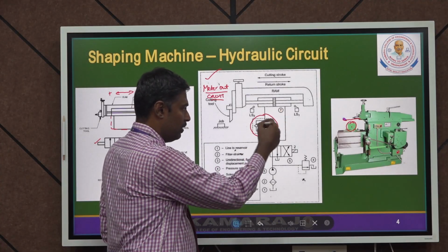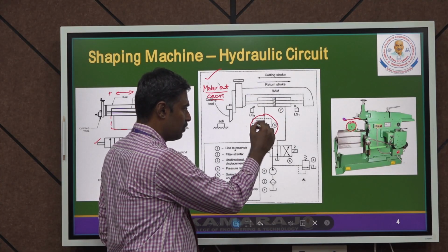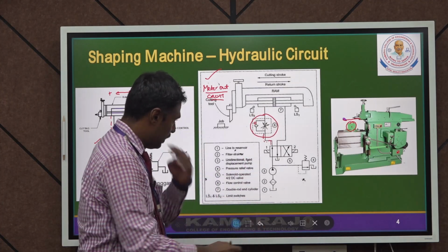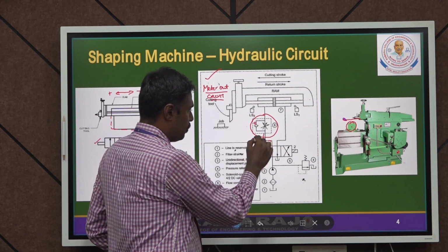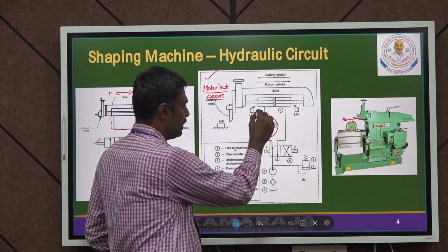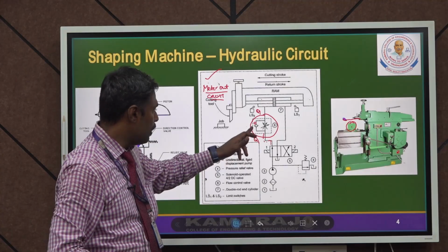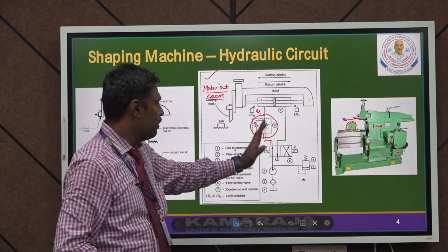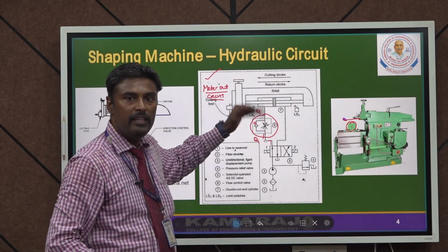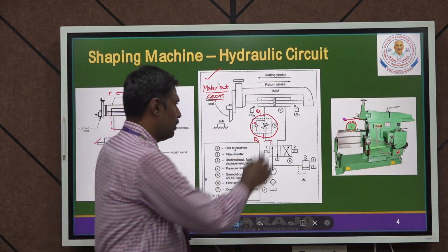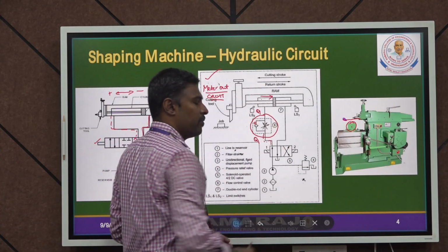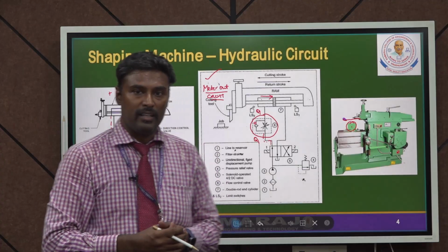In this throttle valve you have a high flow rate. After exhausting, if you release, this check valve will open back. Therefore, if you apply the flow rate Q1, the same Q1 will pass through here. Because of the check valve, the fluid goes from this port to this port in a very fast manner, so the return of this ram is achieved very fast.